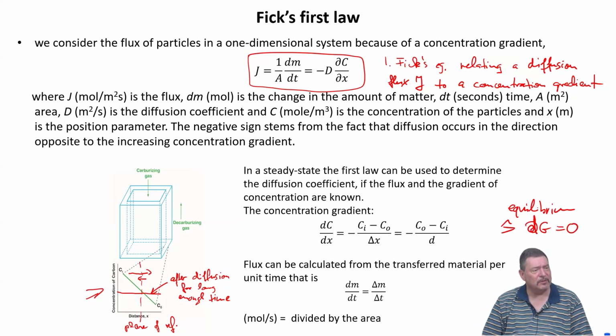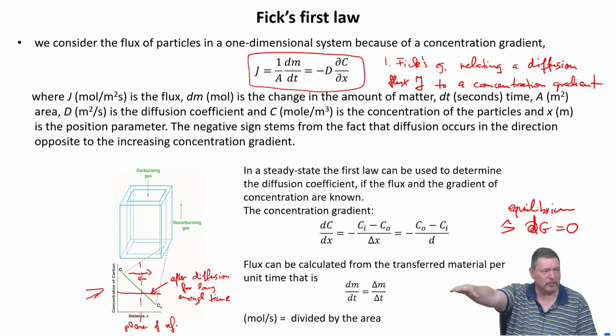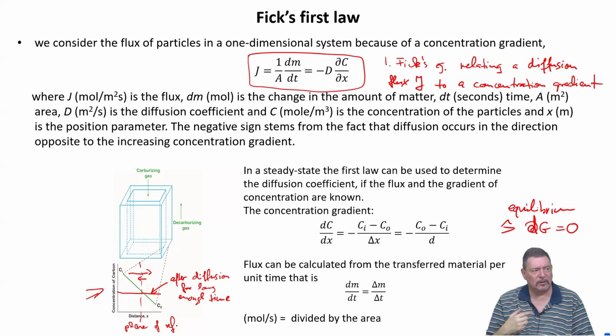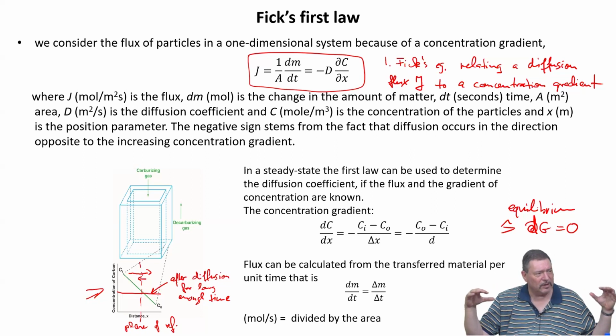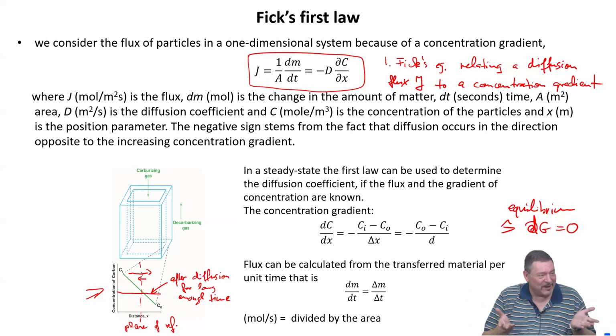So we find the absolute minimum of the free enthalpy. And that means the concentration gradient has been taken out and been leveled off by diffusion. So this is then the total equilibrium. But the flux going from this non-equilibrium distribution of elements with a concentration gradient to the situation where the system is in total equilibrium is an equilibrium flux, so to speak, because you can calculate it by this diffusion equation.